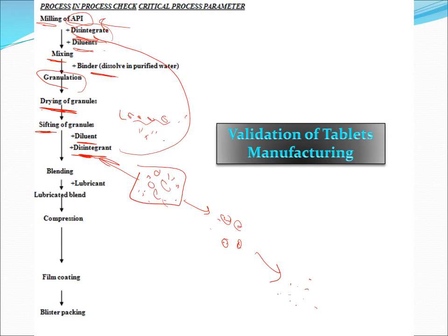into fine powder. And then you will make mixing, and add lubricant at the end, so it will be in touch with the machine, the hopper, to improve flowability, prevent sticking, and then compression. And if you want, there is film coating, enteric coating, sugar coating, then blister packaging. So those are the steps of tablet manufacturing, and we need here to differentiate again